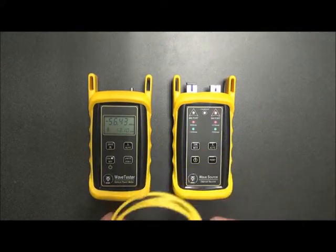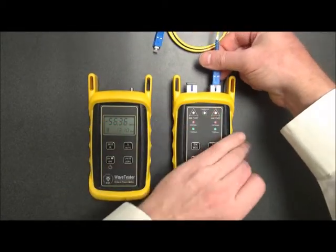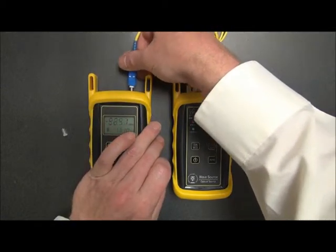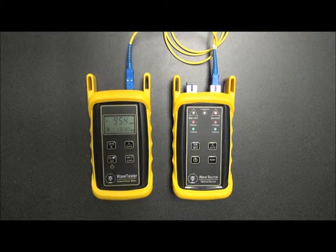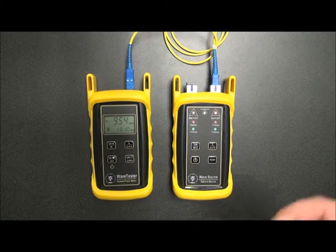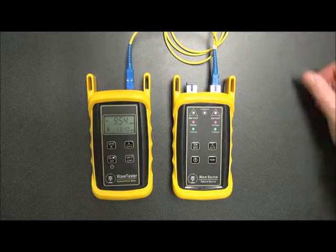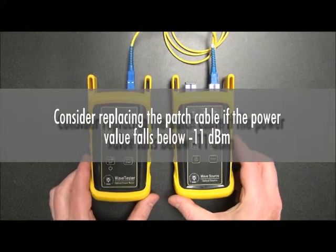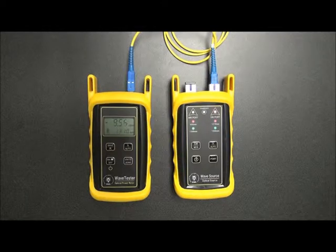Now we take the second patch cable, the patch cable that we will be using to zero out our light source. We plug that in as well. Okay, now as you can see, this is even higher level, minus 9.5. Okay, this patch cable is also sufficient to use. Really what you need to concern yourself with is whether or not the patch cable is exceeding minus 11 dBm. At that point, it's best to consider replacing the patch cable.